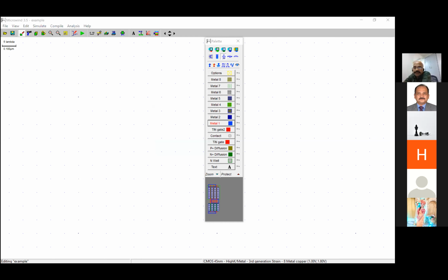I'm sharing these mask files so that in case you want to open and see what went wrong, or something is troublesome in your design, you can always refer to this design which we have just made and perfected. Capacitance 0.1 picofarad, 0.01 picofarad, something small value. Don't keep it too high, otherwise it might be loaded too heavily.